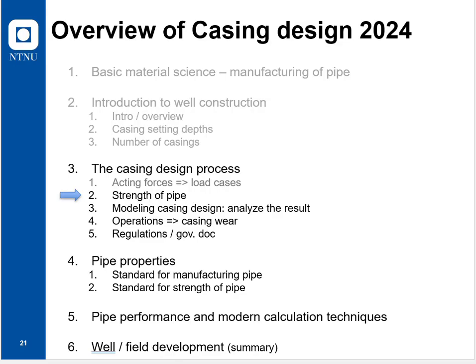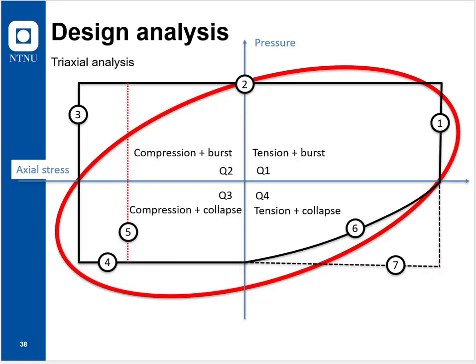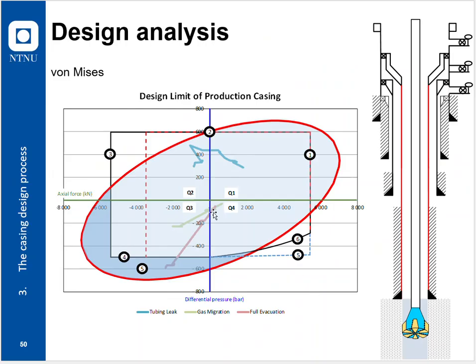Once you know those, you need to select your pipe, and the pipe will appear in the casing design software, for example, stress check and WellCat. They will appear as limitations, and we saw that in a plot like, for example, this, where we'll see the stresses in the well going on like these lines here, and that they are inside our design window.